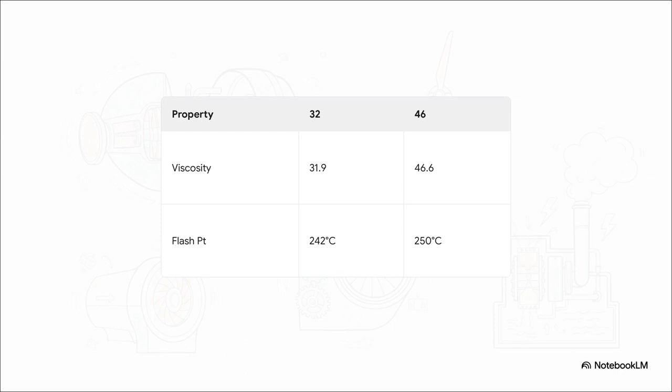Get this, it offers over 16,000 hours of oxidation stability. It's formulated with additive tech that meets incredibly strict Mitsubishi standards for preventing sludge and varnish. And that matters a lot. Inside a turbine, even a microscopic, practically invisible layer of varnish or sludge is enough to throw a high-speed rotor totally off balance, or entirely block a hydraulic control system.